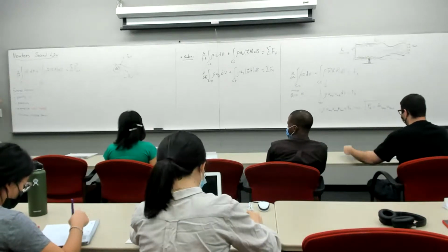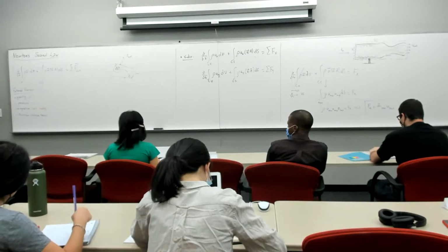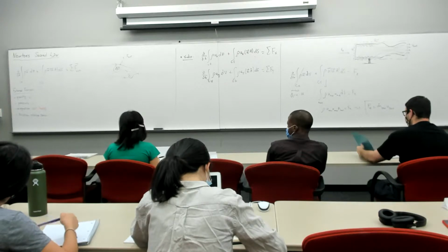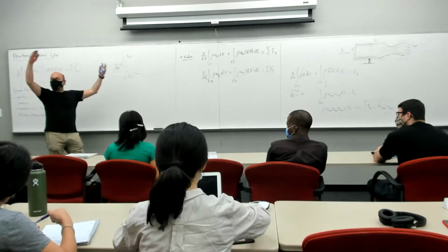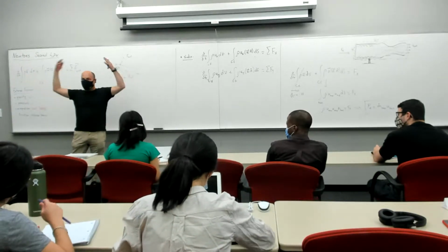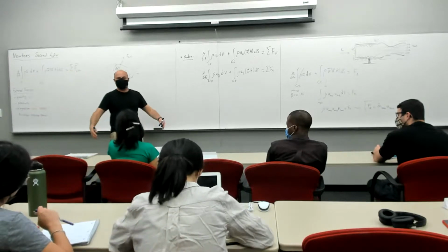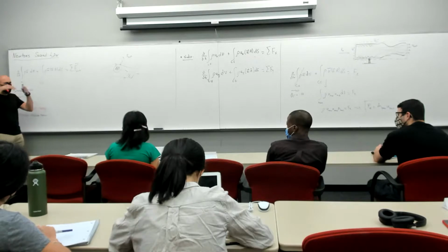There's a further distinction, I'll say that distinction and we leave, between what we call body forces and surface forces. Body forces are forces that act on the entire body of the fluid, such as gravity acts on all of you, right? Surface forces, however, act locally depending on the surface orientation and whatever's going on locally.